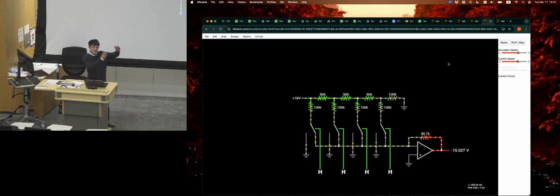So we're basically dividing it every time by 2, and then using that amount as the lowest step of our DAC converter. And then we individually turn on and off each of these switches and add it up to a value on the V output. Hope that makes sense. More or less? Okay, cool.